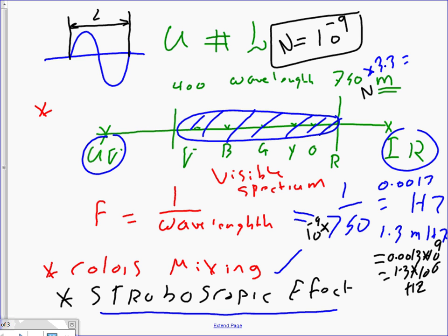Okay, so be aware. What's in it for you? When you do a factory, bring at least 2 circuits from 2 phases, not 1 circuit. Cool? Make sure that you feed the manufacturing floor, anything that rotates, with at least 2 circuits, so things do not look still to the bare eye. So that's your stroboscopic effect.